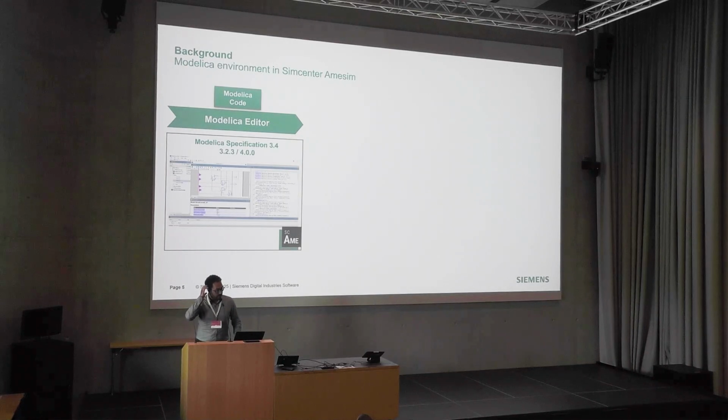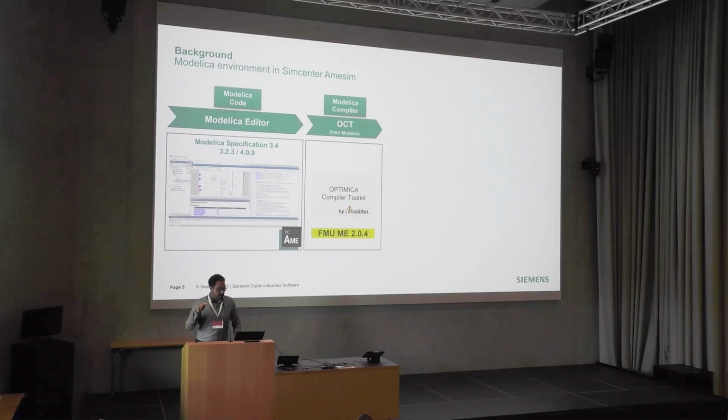How is this Modelica world already implemented in the Simcenter Amesim platform? We have an editor named Modelica Editor, where you can load the different MSL libraries. Right now, we are compatible with the 3.2.3 and 4.0.0 Modelica Standard Library. Between this Modelica editor and the Simcenter Amesim platform, we have the compiler developed by our partner Modelon.